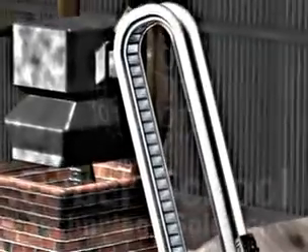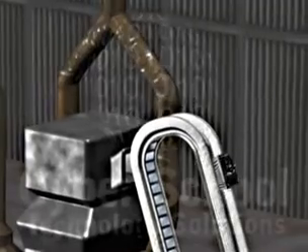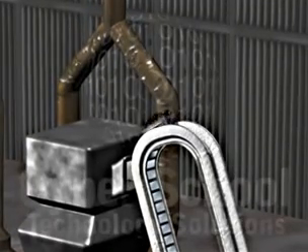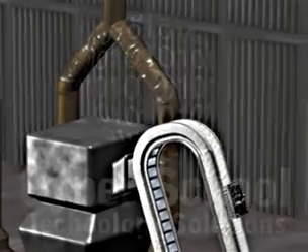The walls of the furnace are made of heat-resistant magnesium oxide bricks. Hot air inlet pipes are called tuyères. Molten iron flows out through the outlet at the base. Slag, calcium silicate, which has a lower density, floats out from the outlet above. In the lower section, carbon burns in hot air and forms carbon dioxide.